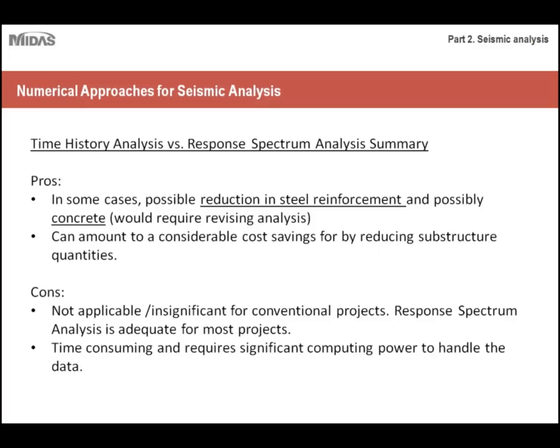So if you decide to go with a time history analysis, just make sure first and foremost, one, that it's worth the investment, and two, that you're properly equipped to handle it. If you don't have a numerical modeling program, it's really not realistic to do the time history analysis, because engineers, especially out on the West Coast, have numerical modeling programs that are very specific to seismic analysis to help them save on the time that they invest in it, because time history analysis is just so prevalent there. So those are the two things to keep in mind. One, make sure that you actually need it, and two, make sure that you're equipped to handle it if you do.